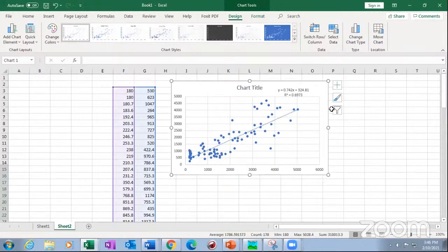Whether 0.7 R-square makes the model satisfactory is completely my opinion. But in general, if you refer to research papers, an R-square value of 0.7 is good. An RMSE value for hydrologic modeling of less than 500 cumecs is good. There are many other criteria. An NSE value, the Nash coefficient, of more than 0.7 is also good.